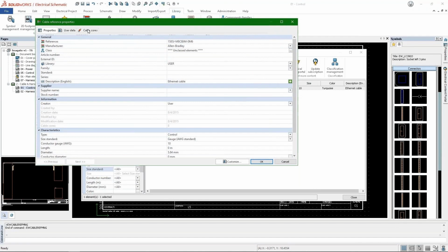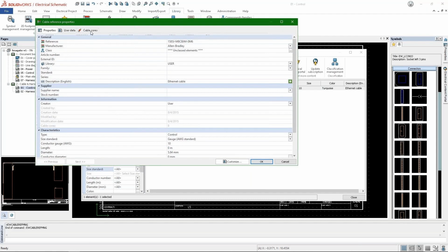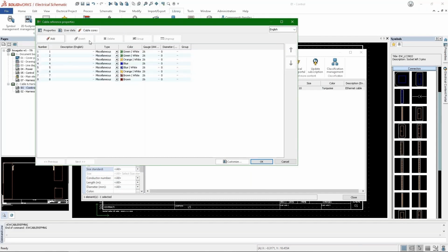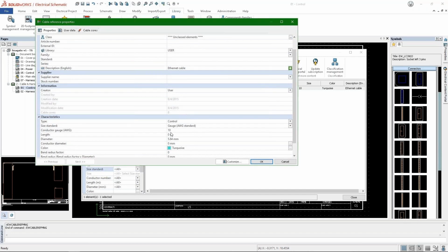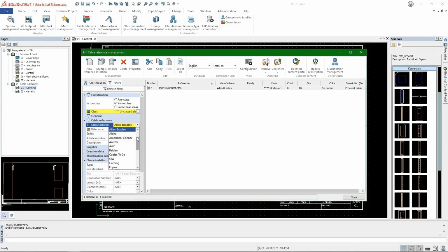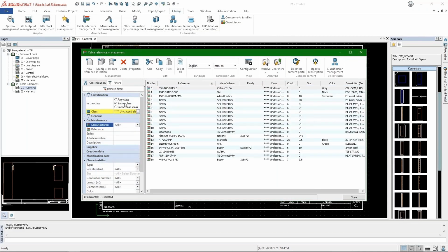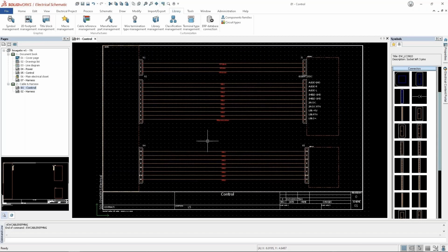So before, you saw me defining some of these general properties, or an area where we could have access to those. On the actual cable, though, I want you guys to keep in mind the cores carry size information as well. So in each cable, even though you define the diameter, we can come in on those cable cores and put sizing information there as well. So you got a few fields that will help drive the appropriate creation of any given cable. You can customize and build your own cable library as needed. But there I've created and defined some cables real quick.